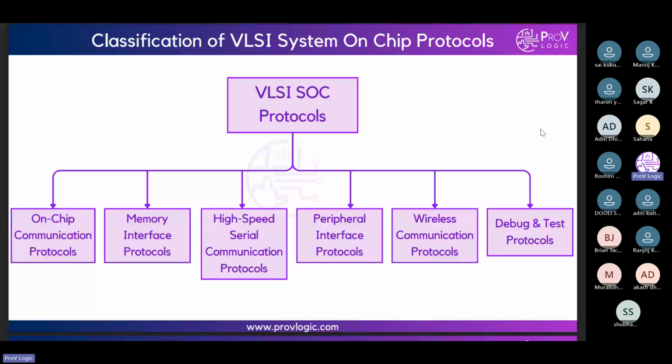Majorly, we have I2C, SPI, UART, CAN, controller area network. Coming to the network side, we have CAN or LIN, local interconnect network. These are different types. Mostly we use them within the SOC, for intra and inter communication. We will discuss both clearly.